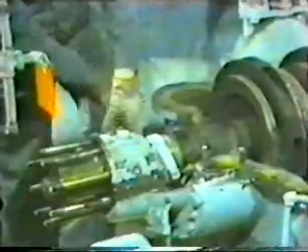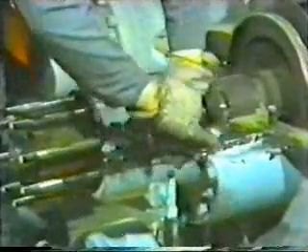The last part of the troubleshooting process is to take steps to prevent the problem from happening again in the future. On certain pumps, some plants may require that you shut down the pump and disassemble, clean, and inspect the bearing. This is because even though there hasn't been any indication of bearing damage, the life of the bearing may have been decreased.